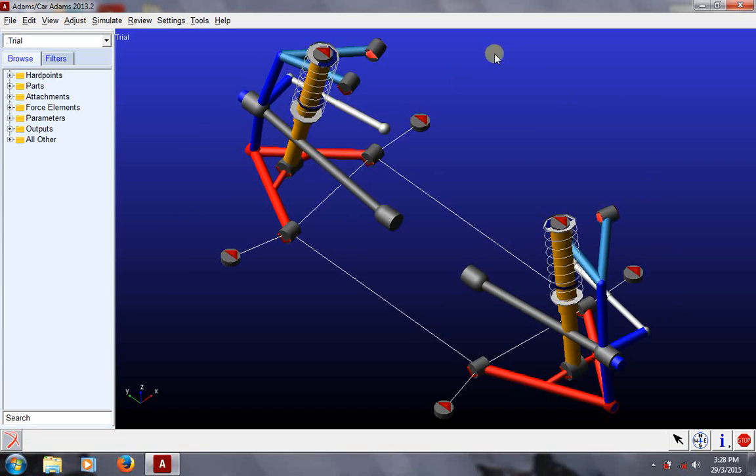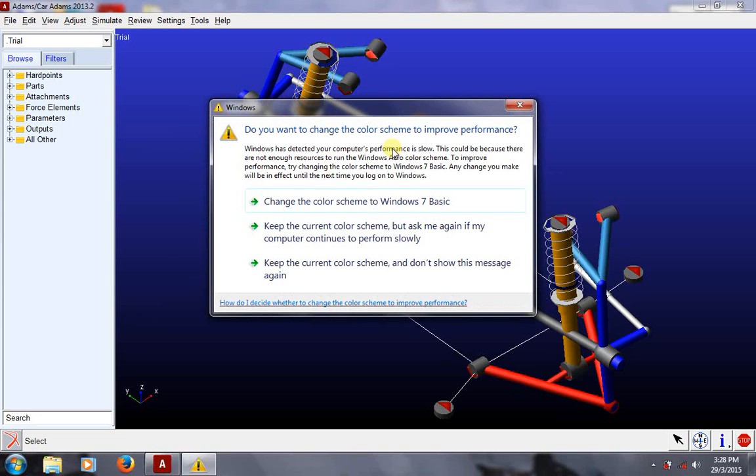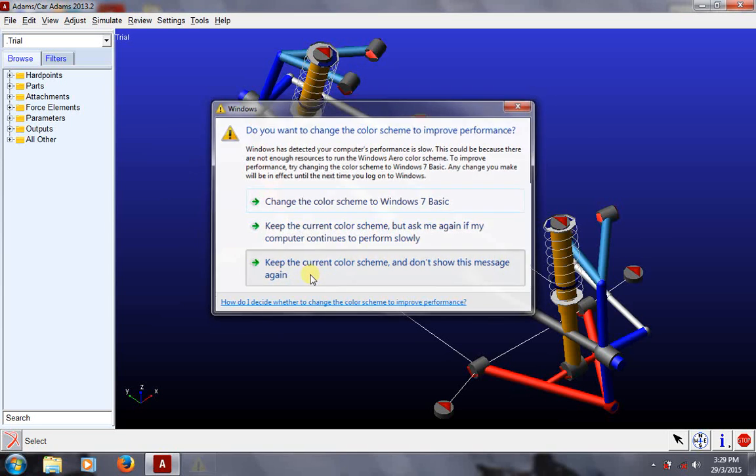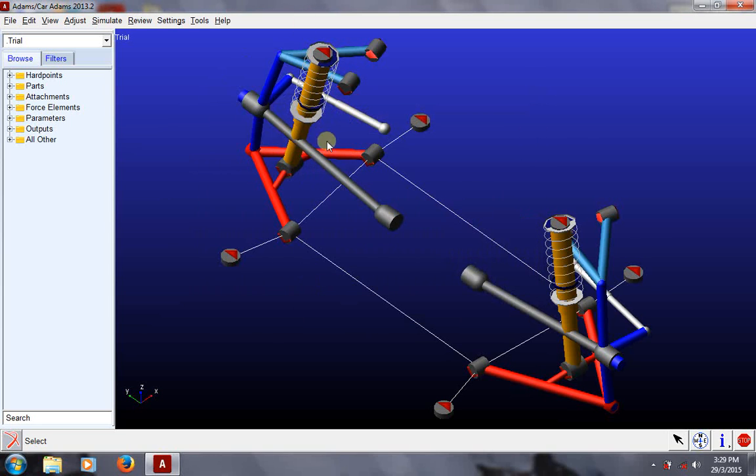Now you see, we got the basic structure of the double wishbone suspension, and with these being the upper A-arm, the lower A-arm, the strut, and even the drive shaft. Also there is the tie rod. Now you must know that the geometry of the suspension is very much dependent on the steering system.